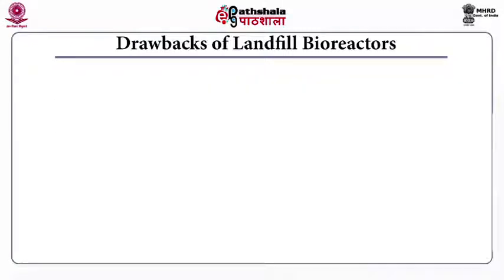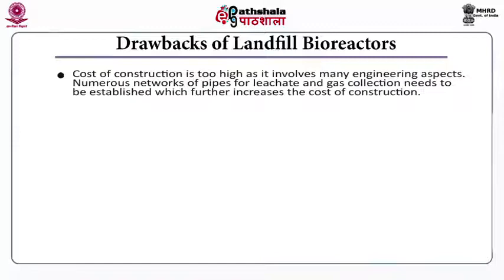Now, what are the drawbacks of the landfill bioreactors? The cost of construction is too high as it involves many engineering aspects. You need a numerous network of pipes for proper leachate and gas collection, which needs to be established properly. Since it involves a lot of waste collection pipes, the cost of construction actually increases, and you require skilled labor for the operation of LFBR, I mean the landfill bioreactor.